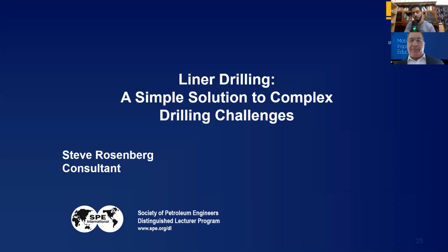Okay. Now, Ibrahim, you got a great question. That's a good question. Now in the steerable or the retrievable systems, you can rotate it with just a mud motor, but the liner itself won't be rotating. Even in that case, you still want to impart some rotation, because rotating the liner is an inherent advantage of liner drilling, like I said, with the smearing effect, that type of thing. So you do want some rotation.